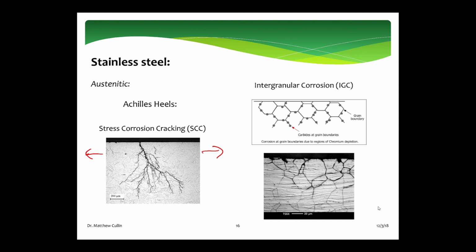So if you see SCC, which stands for stress corrosion cracking, you are going to be very concerned about what grade of stainless steel you're using if you're handling seawater or any sort of solution that has chlorides in it. As the temperature of the solution that you're handling goes up, the prevalence of stress corrosion cracking goes up.